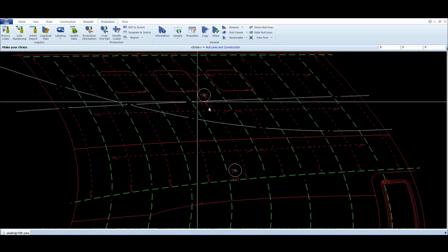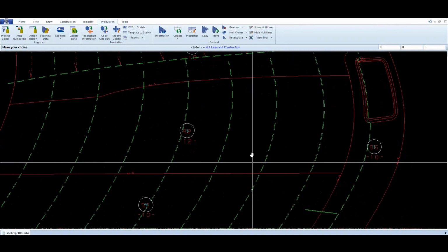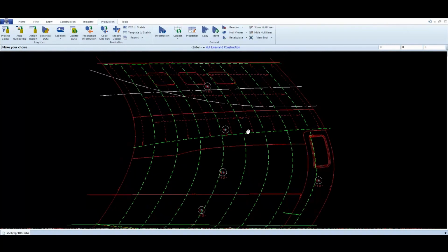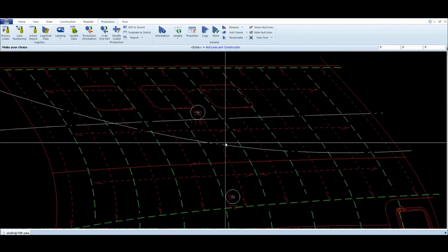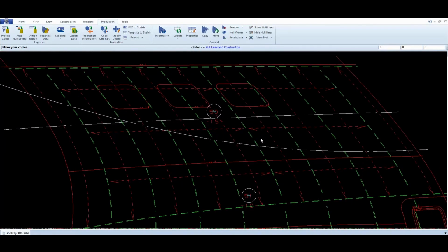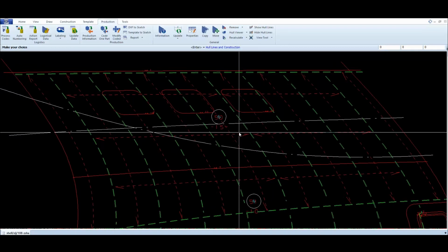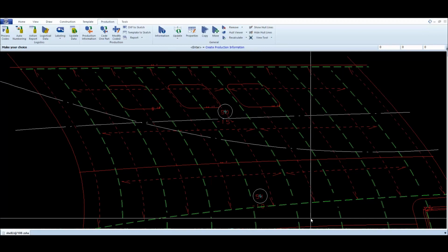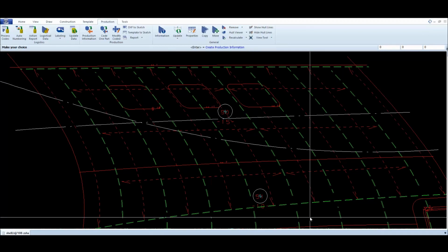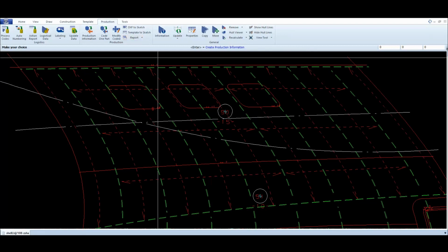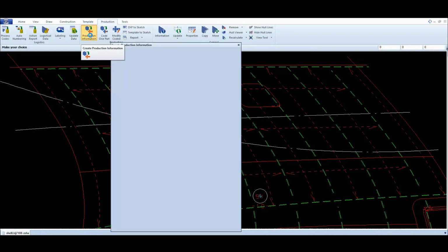We have one shell plate 50 and it ends at 55, so we have 6 shell plates, and they all have now numbers which we will use further in the process when we generate production data and templates. Let's now generate production information for all the shell plates that we have created. In the same Production tab, we will start the function production information.